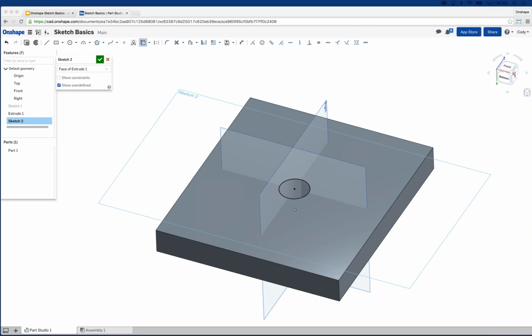Now, a quick question. Can you format text and dimension text ahead of time for the default font and size? And the answer is no. As of today, you select text, you draw a rectangle, and then the rectangle defines it. So it is in a certain order. You select the command, then sketch a rectangle. You can't do it the other way around. Now, that is the use command.